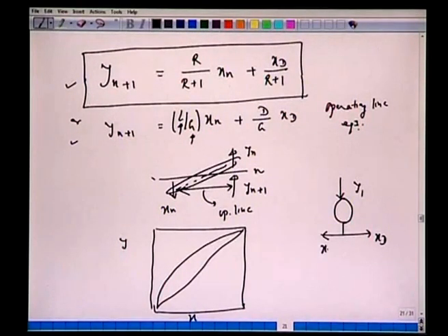This is x_0, same as x_D, same as y_1. This liquid goes to the top of the column, stage 1. We have this y_1, and the liquid which leaves here is x_1; the two are in equilibrium. We have y_2, and so forth.